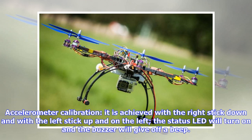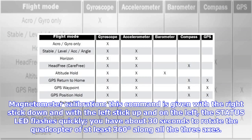Accelerometer calibration. It is achieved with the right stick down and with the left stick up, and on the left, the status LED will turn on and the buzzer will give off a beep. Magnetometer calibration. This command is given with the right stick down and with the left stick up, and on the left, the status LED flashes quickly. You have about 30 seconds to rotate the quadcopter at least 360 degrees along all the 3 axes.